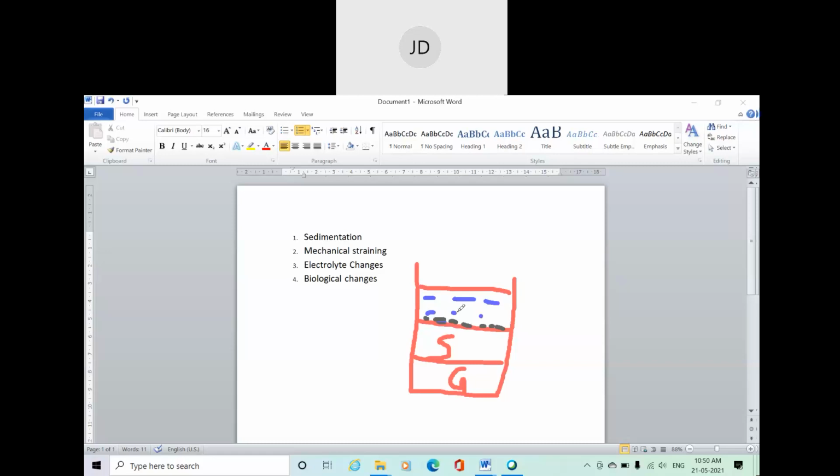And that carbon dioxide coming from the oxidation of organic matter by bacteria and virus can be used by some autotrophs present in the impurities layer. Autotrophs means what? You have also seen some green colored grasses, green colored living things near the surface of the filter, right? So they are basically autotrophs, for example algae and plankton.